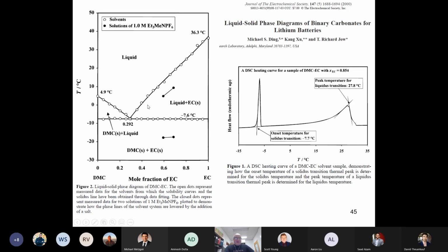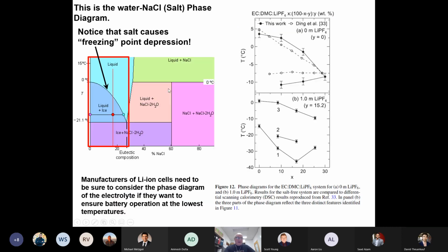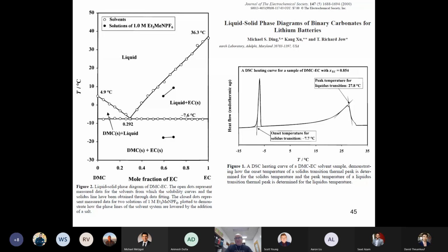Yeah, there's a horizontal line you draw here. Let me go back to the previous slide. This horizontal line is called a tie line, and it joins the two phases that coexist together at a particular temperature and composition. So you can figure out the composition of the liquid phase by going to this point and reading down. So this is like 25% NaCl in water at this point. Okay, cool. Thanks for that question. Any other questions? Okay, hearing none, I'll continue.